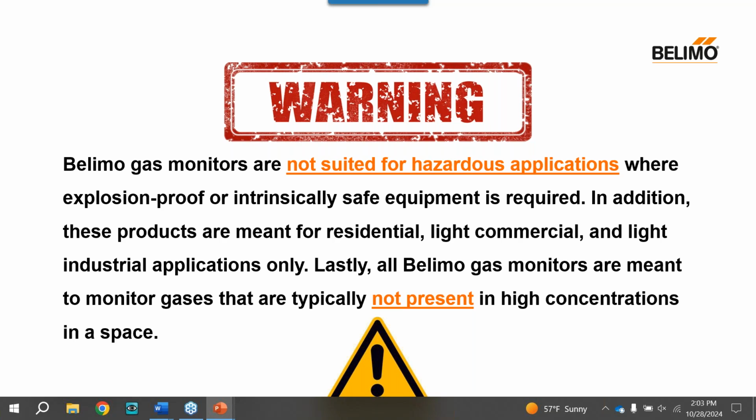Well, if you're using these gas monitors in a parking garage, typically CO and NO2 gas levels aren't high enough to poison somebody. However, if a car does idle there long enough with the engine on, gas levels could become toxic, at which point the gas monitors are there to sense the increase in gas, alert, and ventilate the space to get levels back to normal. So basically, the more gas that the gas monitor detects on a normal basis, the quicker the sensor modules, which are the physical part detecting the gas, will be used up and need to be replaced.